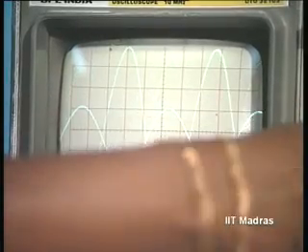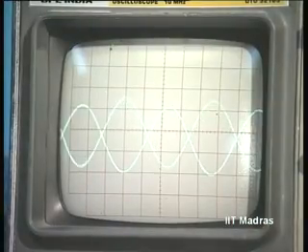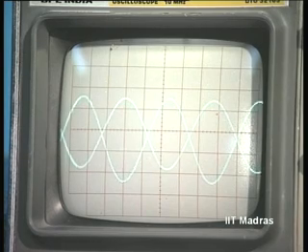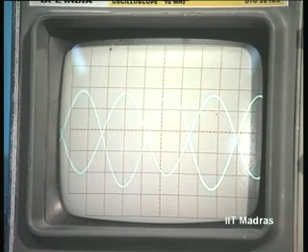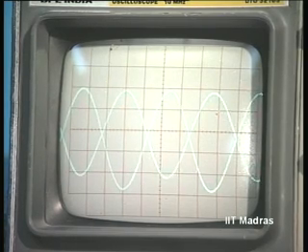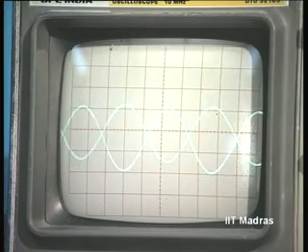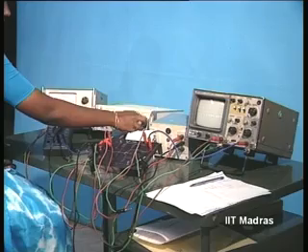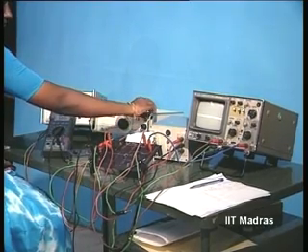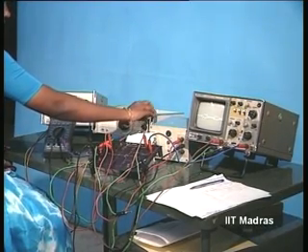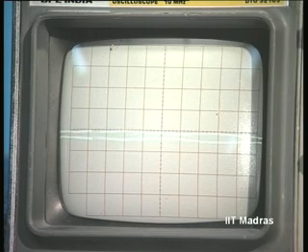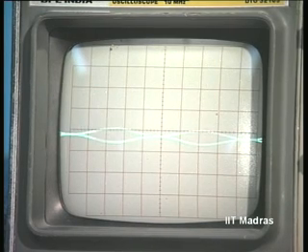Now distortion will occur only due to cutoff and saturation. The other distortion, which occurred earlier due to nonlinearity of the device, disappears. This is because it has been made linear by putting a series resistance of 2.2 K in series with the 25 ohms of the transistor. So just increase the signal level.